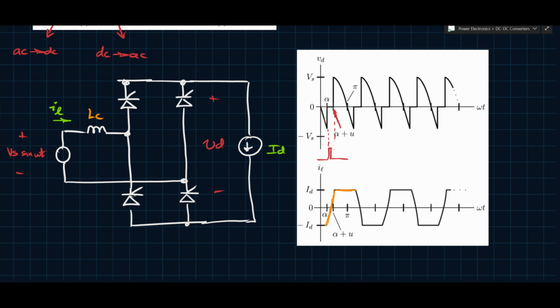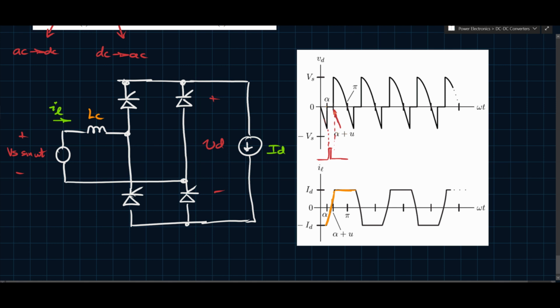And the commutating voltage is therefore the voltage that is applied in order for this commutation to take place, or the voltage that is applied to the inductor while this commutation is taking place. Because if VD becomes 0, then that means the voltage across this inductor, we can call it, let's say, VL, will be this Vs source voltage minus whatever's on this output here. Well, again, assuming those are conducting. But if all of these are conducting, basically you've applied only Vs there. So Vs is the commutating voltage.